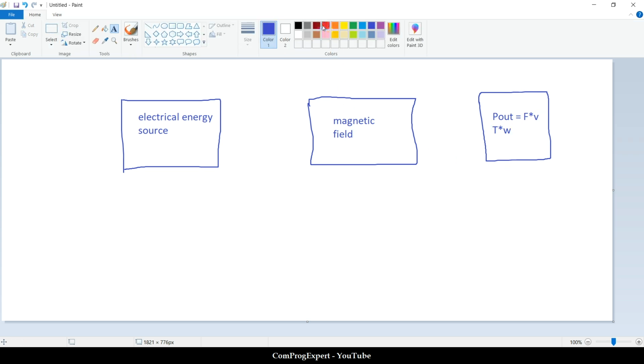So here, the input energy minus I squared R loss, right? This energy is received in the magnetic field. We have an increase in the value of the stored energy in the magnetic field. Also, we have losses, hysteresis loss and eddy current loss.